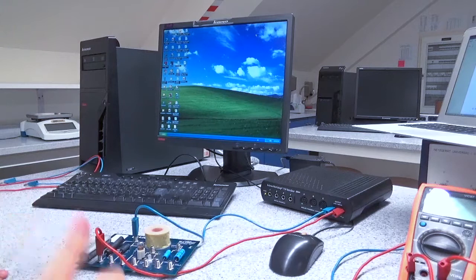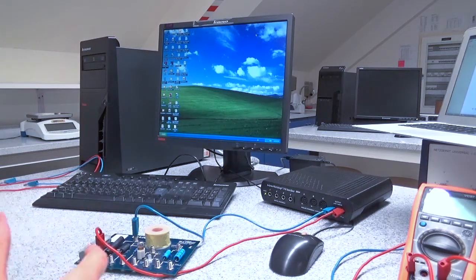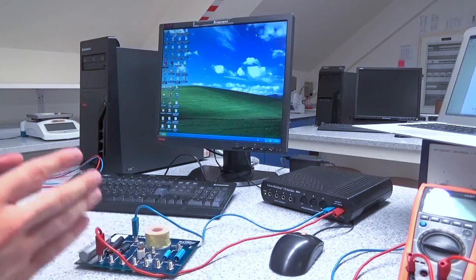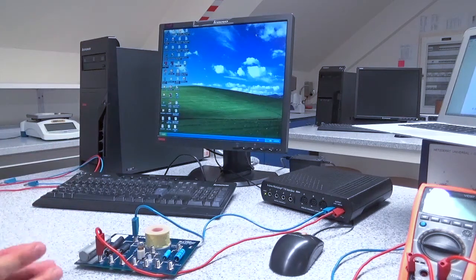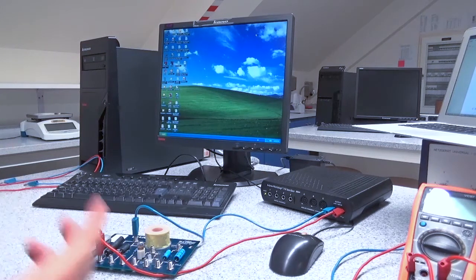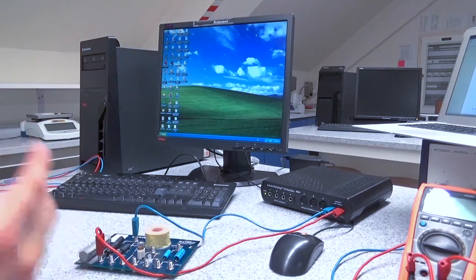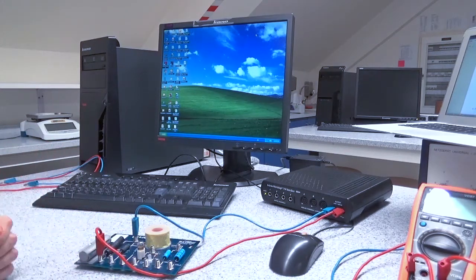In the first part of today's experiment, we are going to be studying the case of ohmic devices. We saw before that for an ohmic device, the relationship between the voltage and the current is a straight line relationship, which is an indication that not only the voltage and the current are directly proportional to each other, but also that the slope, which is none other than the resistance, is a constant for an ohmic device. It's always a constant for an ohmic device.